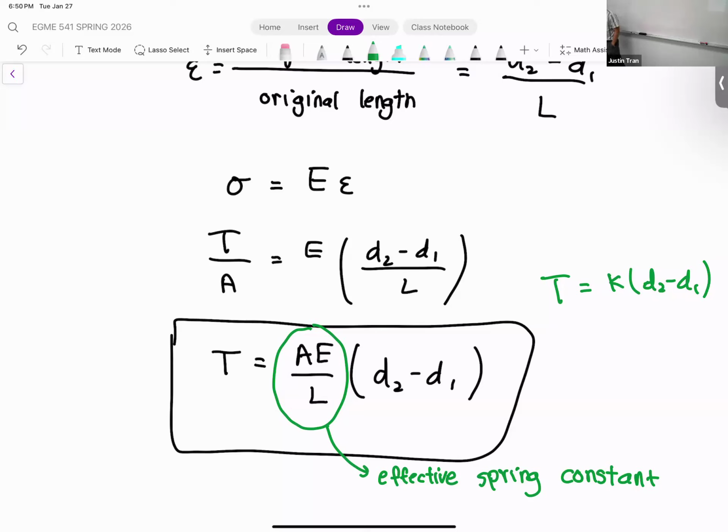You'll see when we get there why that's not practical to do by hand, because for these problems the element stiffness matrix is just 2x2. But for frames, in the most general sense, the element stiffness matrix is actually 6x6. So instead of getting 4 values, you're getting 36, and then you're assembling that into a matrix. So that's definitely the whole point of the class. You're all going to hate it.